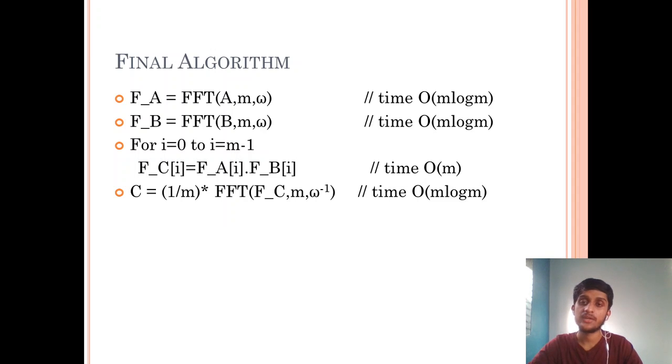So what we can do is apply the fast Fourier transform on both the input signal and the impulse response and convert them into the frequency domain. In the frequency domain, it's just the dot product of these two, the input signal and the impulse response, and then we can apply an inverse Fourier transform to get back the output signal in the time domain, right? So this is one of the applications.